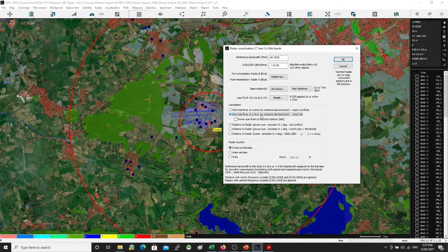Okay. And I know you want to use the combined effect of multiple sectors, but I'm usually taking care of this using the benchmark model that I talked about. The Omni antenna was 25 dBi. So this is my benchmark, which will be the very, very worst case scenario. Okay, so you could use the combined analysis.